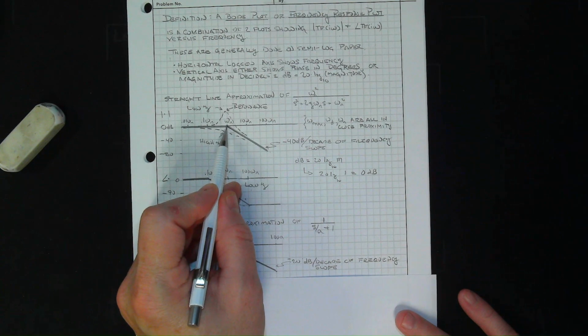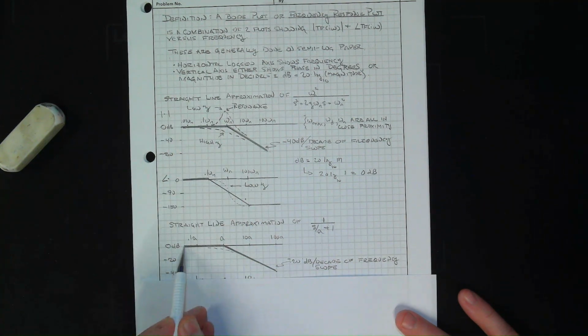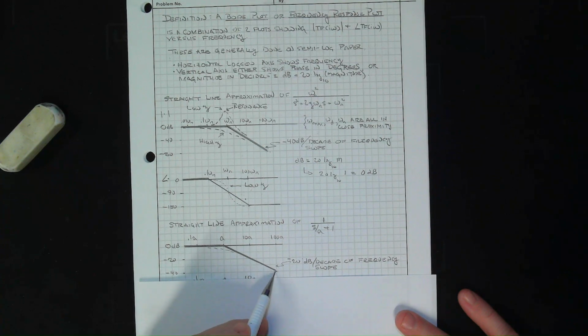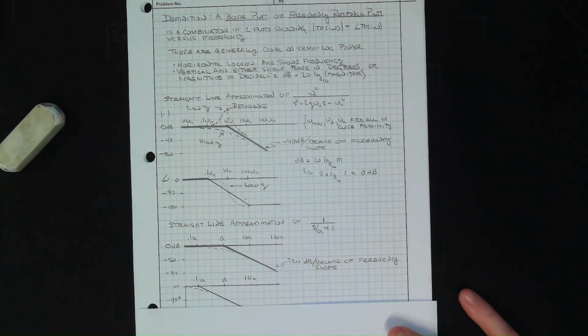This is right here. So here we did it at omega n. Here we're going to do it at A. And we go straight, and then we fall off at 20 dB per decade. All right, so that's a factor of 10 for every decade of frequency. And this is a very good approximation. This is within about 3 decibels or so here. So in reality, it's going just a little bit below. It's asymptotically coming off the horizontal, and it asymptotically matches up with this minus 20. Okay, pretty good approximation.